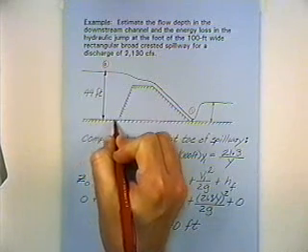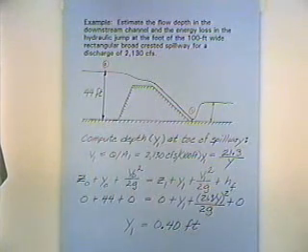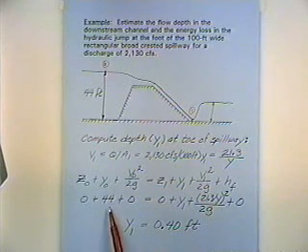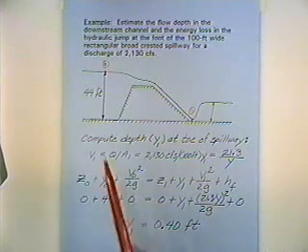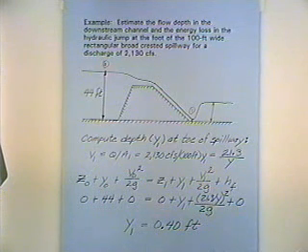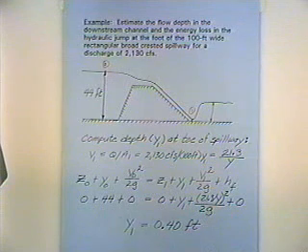I will just take this line, and that'll be our reference datum. With that as a reference datum, Z0 is 0, and the depth is 44 feet. At that location, for the velocity head, we're going to assume 0 velocity. Upstream of the dam, back in the reservoir, the reservoir is very wide, so the velocity is very small. Assume 0 velocity.